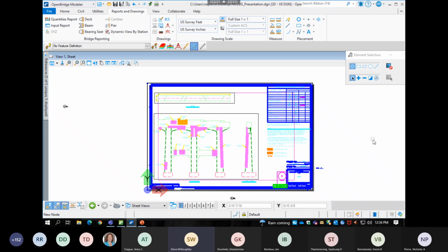So what Edgar did at TxDOT, in his barrier library, he has barriers, just your basic concrete ones without railings, and he has some with railings, where he basically created the outline of the barrier with the railing so that if you did cut a section, the section's going to look correct. But modeling wise, it's incorrect because it's really just an extruded 2D shape along the deck.